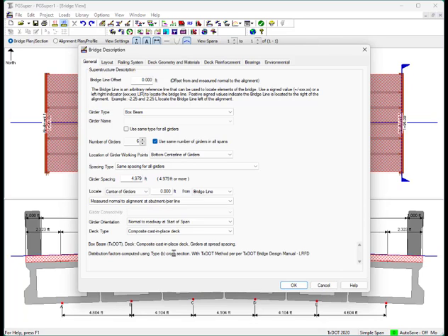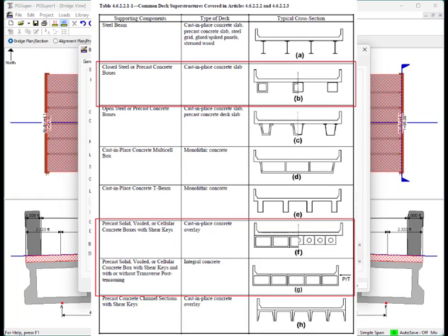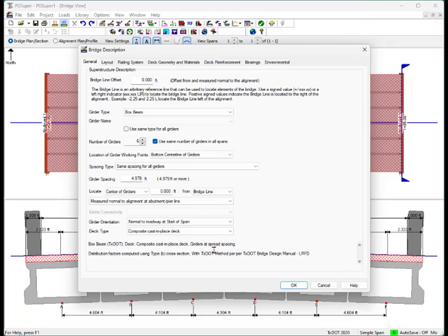Let's bring up an image from the AASHTO LRFD Bridge Design Manual to look at the bridge types. Now, as you can see in this figure, the type F and G are adjacent girders, and they're connected together to avoid motion between the two adjacent girders. But now we have a type B, and that looks like a widely spread girder. I wonder what's going to happen here.